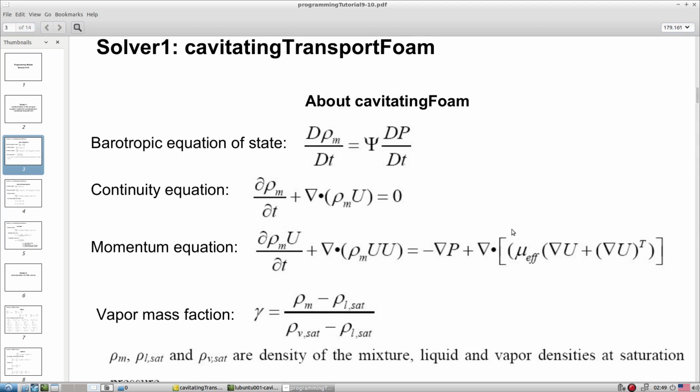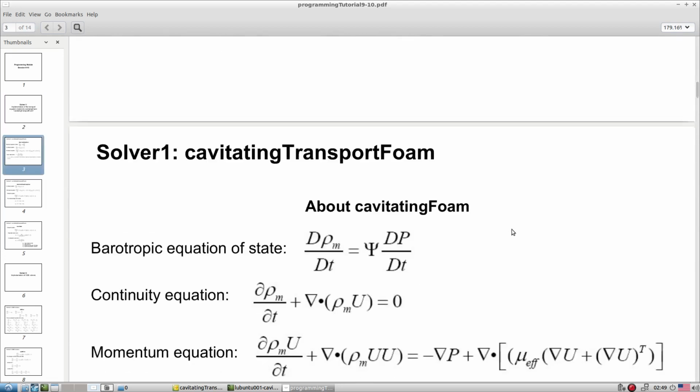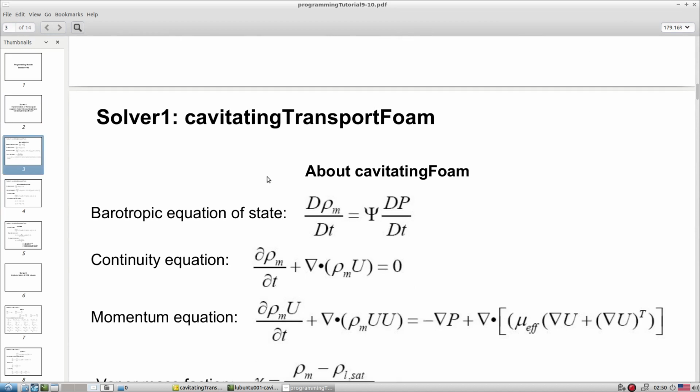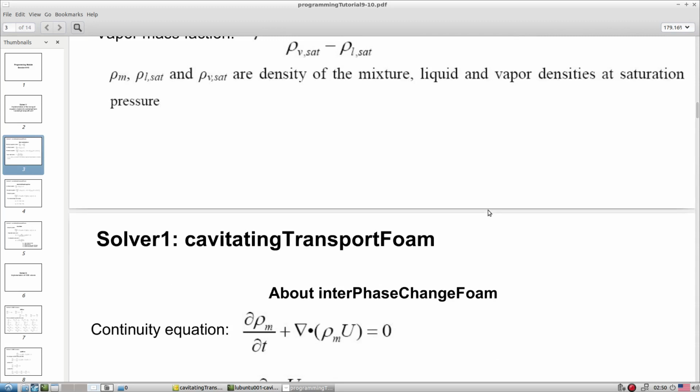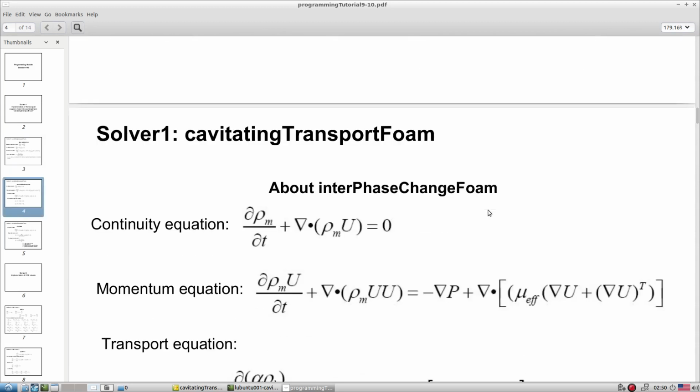At the beginning, what we saw is that this particular cavity transport form was a compressible environment, but we want the incompressible environment cavitation form. That's why we adapted the alpha as a transport equation, plugged it here and resolved the dependencies, and all these things we explored with this particular tutorial.